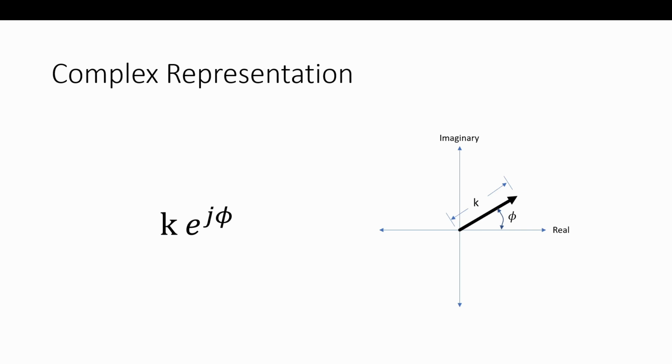And to get your head around the spinning phasor. A spinning phasor representing a single tone and frequency. And the idea of this, when you see this math, if you haven't seen it for a while, it's just magnitude K, angle phi. That's all it is. e to the j phi, magnitude 1, angle phi. So your I and Q are the real and imaginary axes, and we have this as a representation of having a magnitude. It's a phasor, and here's the angle relative to the real axis.